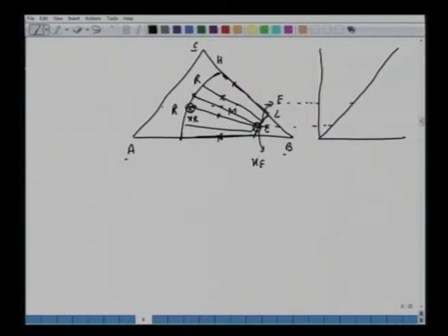All right, so one can show that you will get one coordinate. Again, you do the same thing we did earlier when you have taken the projections like this and extend this component here. So this will represent your E and R. This coordinate which comes from here is XR, and what you are reading here is your Y. So this YE is the extract phase composition, XR is your raffinate, and you get this line.